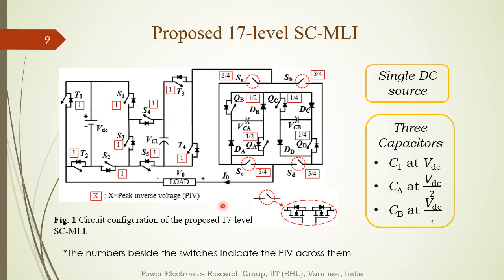So the peak inverse voltage of the SMLI is within the input DC voltage source. A single DC voltage source is utilized, and the three capacitors are inherently self-balanced because of the structure of the proposed SMLI, where VCA is VDC by 2 and VCB is VDC by 4.